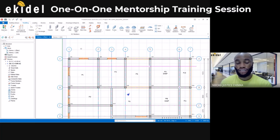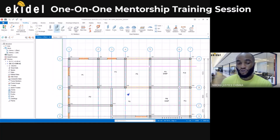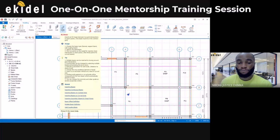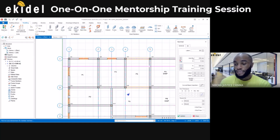Now on this model, we have the column. This wall you are seeing here is for a reinforced wall and not for block walls. So I will skip that and then move to beams. If I click on the beam, you see that they have two options, normal beam or wall coupling beam. We are dealing with normal beams, which are the floor beams. So I'll click on Normal Beam. It will now display this dialog box for me.